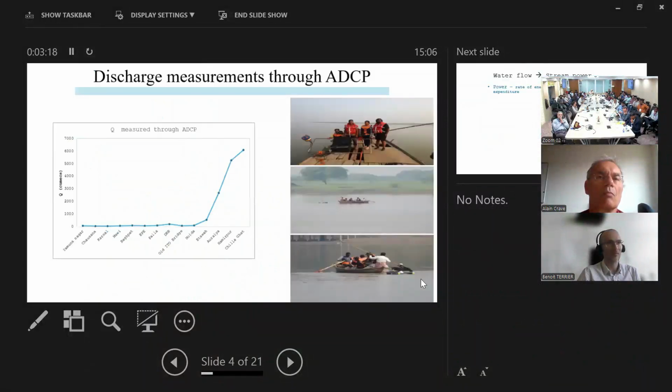Besides this, we also did ADCP surveys from the mountain front to very close to Pratappur, just 100 kilometers upstream of the confluence point, which shows that the water flux coming from the Kraton area is significantly higher compared to the Himalayan river. So hydrologically, it doesn't behave like a Himalayan river system downstream. It behaves more like a Cratonic or peninsular river system. That is the hydrological data. So 20 years of CWC data set, and then 1 year of our cross-section data set support that part.